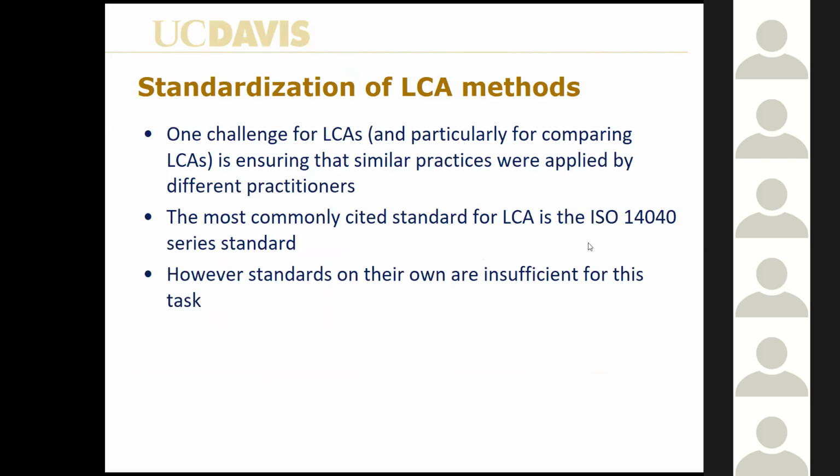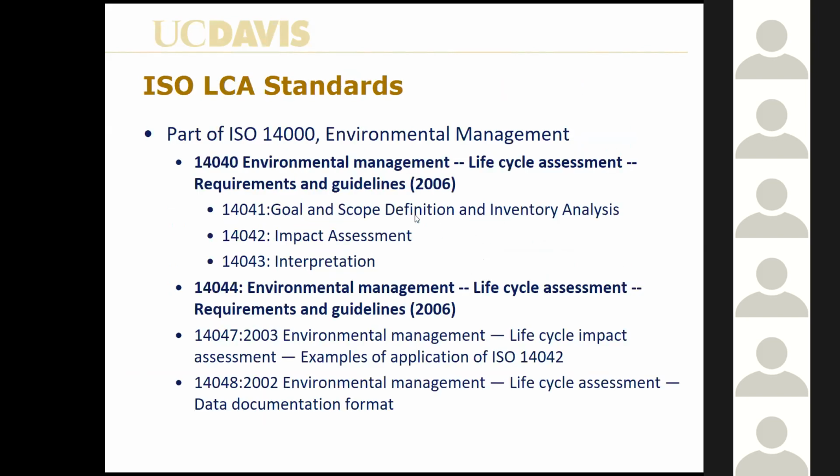So the ISO here is the International Organization for Standardization. And one thing to point out is that this is a very general standard because it applies to any product, not just, for example, asphalt pavements. And so a lot of times we find that the standard isn't quite sufficient to ensure that studies are done in very similar ways. In any case, we still use these as an important guide. So here I've listed the standards that apply to life cycle assessment, 14040, 44, and then there are a few more in there, and I know we'll hear about EPDs later, which also are subject to ISO standards.